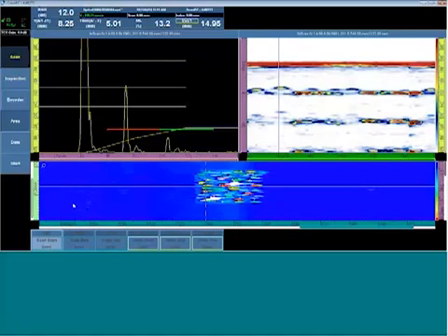So we would build the C-scan one part at a time, one stroke at a time, continuously. The software will not allow you to configure a C-scan that exceeds the capacity of the instrument to save the data file. For most MX2s, that's 300 megabytes. For the first generation OmniScan, that was 160 megabytes.